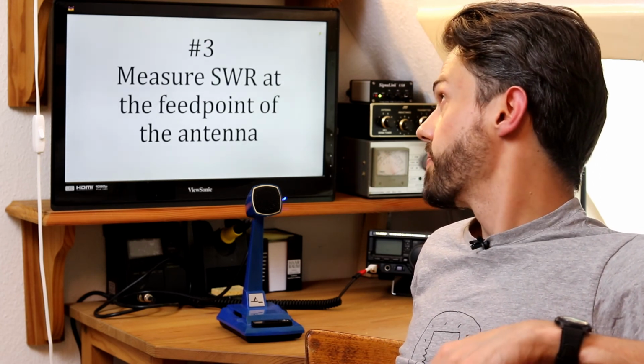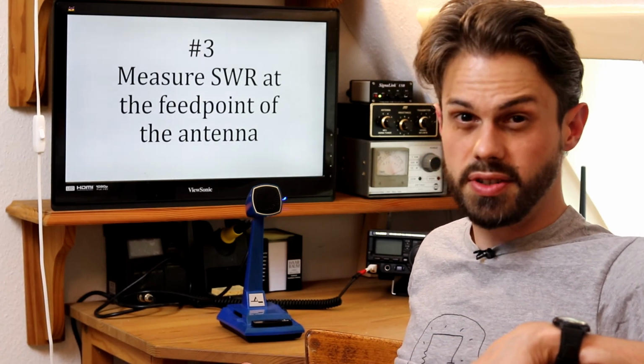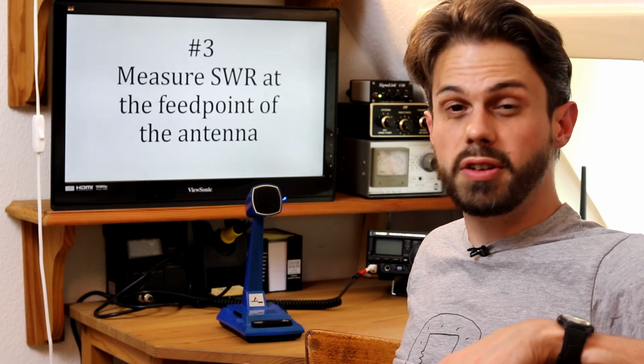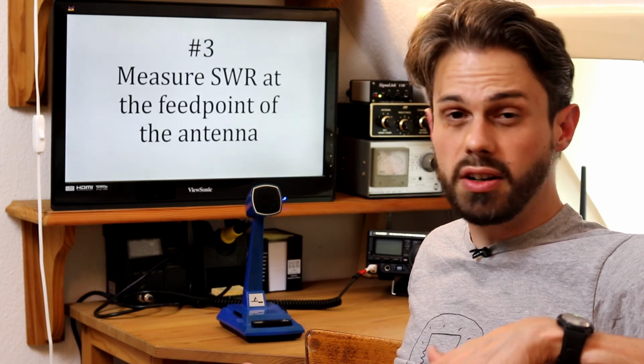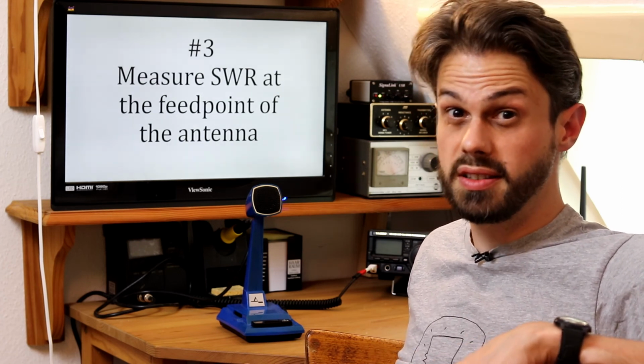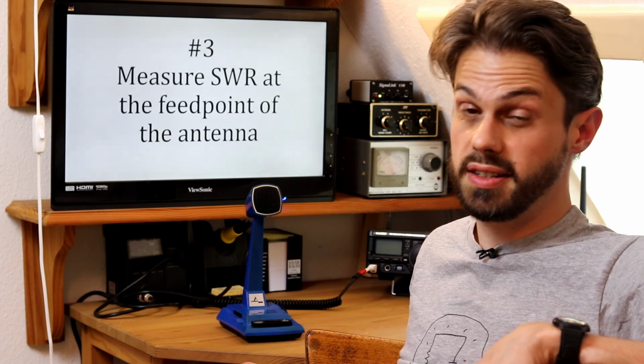Third lesson. Measure SWR at the antenna point, not at the transceiver end. This is important, especially if you're installing a new antenna at your home QTH. Please do yourself a favor and measure it at the antenna point and find out what the situation really is like, because otherwise you can be easily misled and deceived.